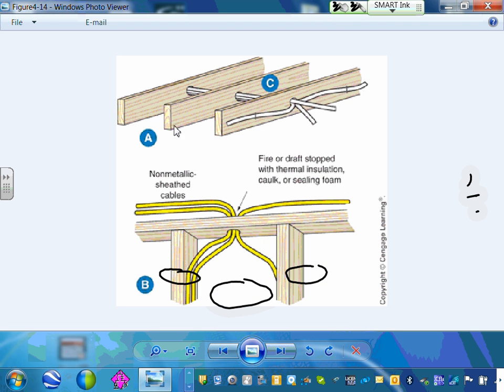When you're drilling your holes, guys, you can group them. Thermal insulation. So like here, you bring all your cables. If you put thermal insulation here, so you thermally insulate this, then you have to derate. So how many cables? Let's just say this is 14. No, should be 12. 12 two-conductor cables. 1, 2, 3. So 3.